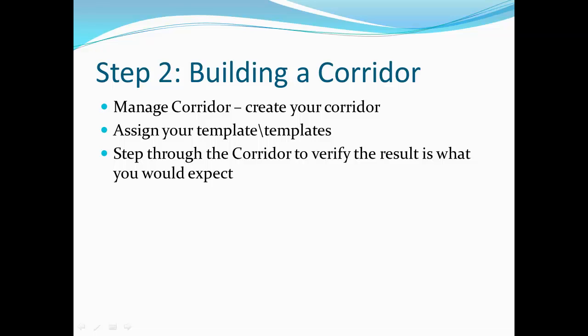What's important to note is that up to this point, you have not actually processed any sections. Roadway Designer offers the ability to step through the cross-sections and make sure that the template is working without having to process criteria first. It's quicker than criteria, where you often had to experience many iterations of failure, crashing, and hard-to-find issues before you could even see if you were getting the results you were looking for.